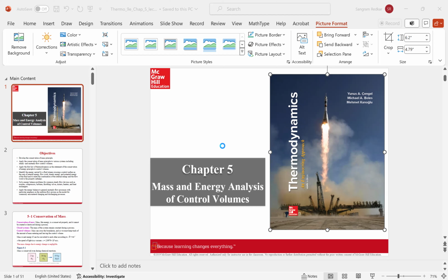Now I want you to understand the difference between the liquid flow and the gas flow. Whenever we are looking at the liquid flow, we assume the temperature of the liquid at intake and exhaust is the same. So typically we ignore the enthalpy, and instead we consider the value of pressure energy. But when we are looking at the gaseous medium, we observe that the temperature could be different at the intake and the exhaust, and that gives you this equation for H, which is enthalpy, kinetic energy, and potential energy.